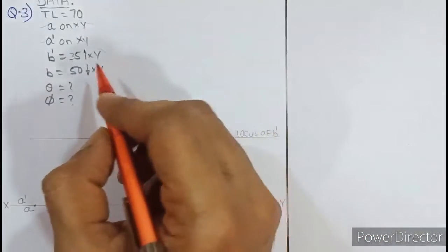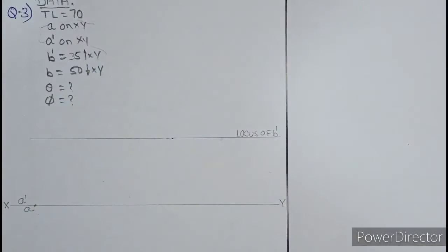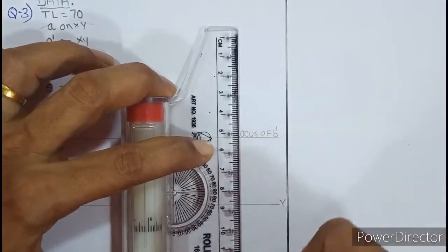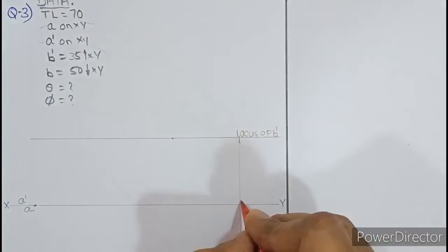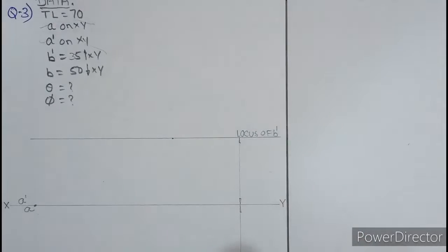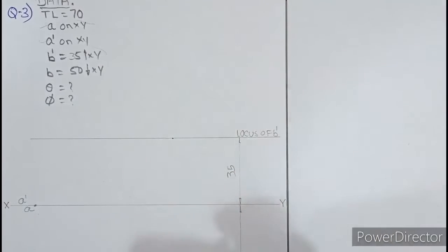But as I told you, in projection of lines, you have to only show horizontal and vertical dimension. Inclined dimension need not be shown. So we need to show 35 and 50 over here. So from here, we can draw a light line, and we can write 35 above the line and along the line, and 50 over here. So as per orthographic, this is called above the line. So that is how all the linear data is being plotted over here.